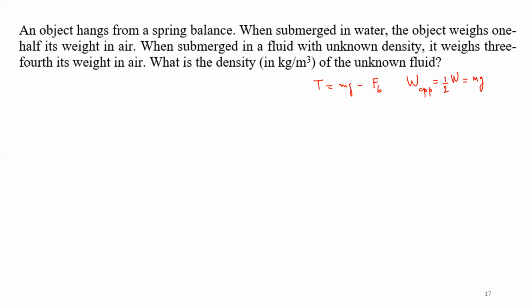This is equal to mg minus the buoyant force. So I mean it's fully submerged, so the buoyant force will be mfg. So it will be rho f, rho water, because at the beginning I'm talking about water, right? So rho water multiplied by the volume of the object, because Vf will be equal to V, which is the volume of the object, multiplied by g. So this is in water.